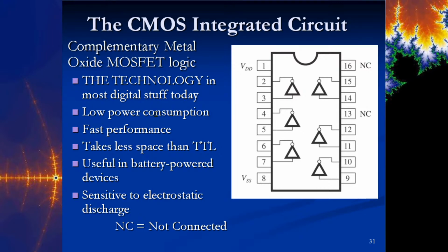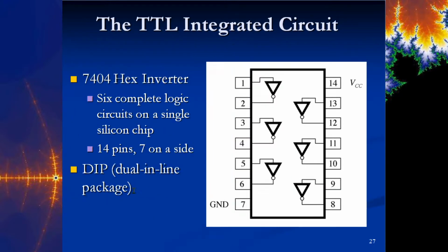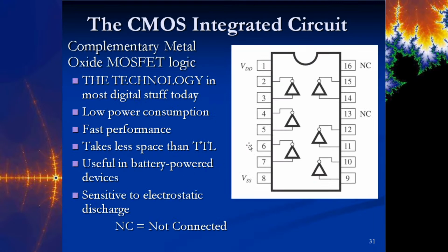So the high voltage output, so like on a TTL chip, if I were to measure the high voltage output, as long as it's above, I think 2.4 volts, it's considered a high. Okay? If you were to look at this, the threshold is a little bit different. Okay, so it might accept a high at 2.0, whatever it is. So it's a little bit different in how they operate.